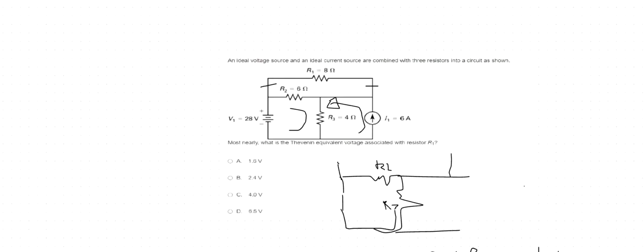So from there, we would use mesh analysis. Why are you going two different directions here? You can't go two different directions with the meshes. You've got to use one uniform clockwise direction. That means you've got to get rid of this arrow right here. It's going wrong? That one? They've got to both go this way, clockwise.